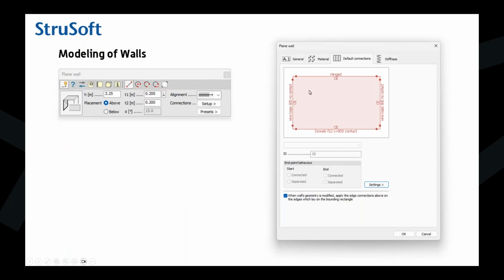If you go to the settings of the wall, you see this picture on the right hand side. All of these, like the behavior model of the connections on the right, top, bottom, and left hand side, are built into this preset that you save and use when you draw models. And if you modify a model, this will be automatically updated to the corners of the element. Then we have another thing that we talk about later. These are corner topologies, how corners are connected to surrounding elements, and we will look at what these do. You can access all of these properties with this big button in the wall tool.